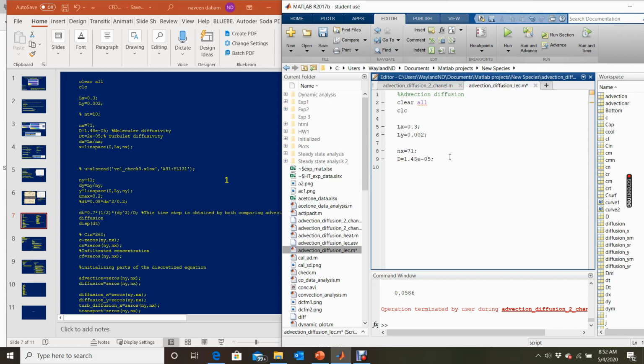And dt is the turbulent diffusivity. Actually I didn't mention the turbulent parts in the governing differential equations, because the flow is not entirely turbulent. However, for greater accuracy there is still a possibility that a small turbulence can occur, even though we are considering the laminar velocity profile. So for that sake we are also writing turbulent terms in our code.